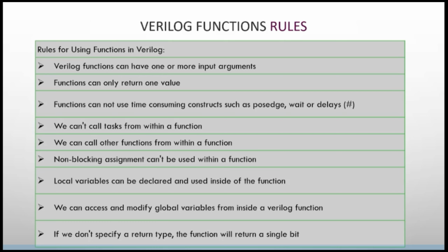Also, one important thing while you are writing functions is that functions should not use any time consuming constructs. You shouldn't use at the rate of posedge clock or delays, or non-blocking statements in case of functions, because all this will represent some time delays, which is not possible in case of functions. So when you are using any time delay constraints, it is better to use task instead of function.